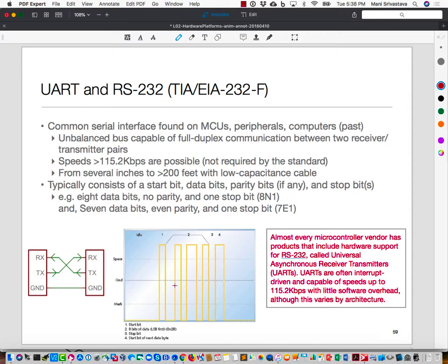And then what happens is when we send the data out, again, remember serially, this is on one side, one wire. There is a start bit and a bunch of data bits and then a parity bit. What is a parity bit, anyone? And then finally a stop bit. What is parity? Yeah, how does it work? What is parity of a number?